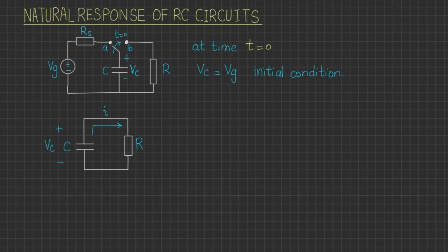We know that as the capacitor gets disconnected from the voltage source, its voltage cannot reduce to 0 immediately. The energy stored in the capacitor will be slowly released, consequently preventing an abrupt change in capacitor voltage. At this time, the expression for the circuit using Kirchhoff's current law can be written as follows. After rearranging, the equation can be written as follows.